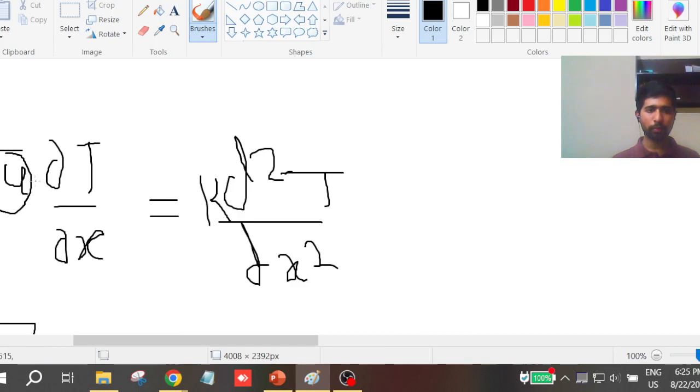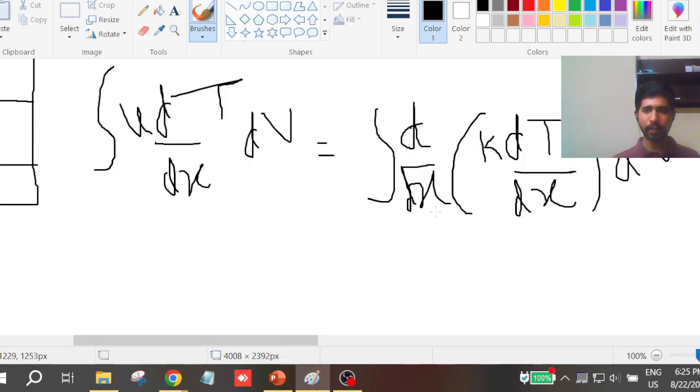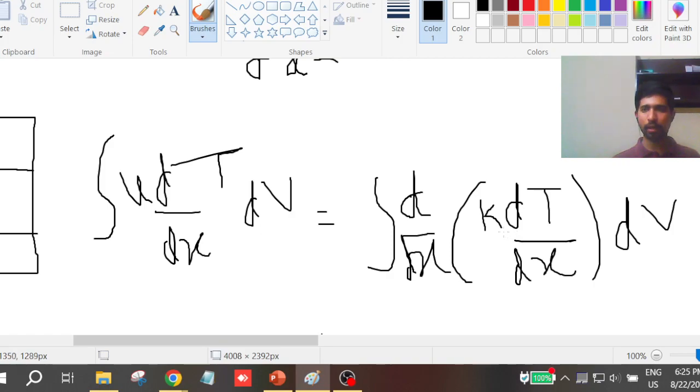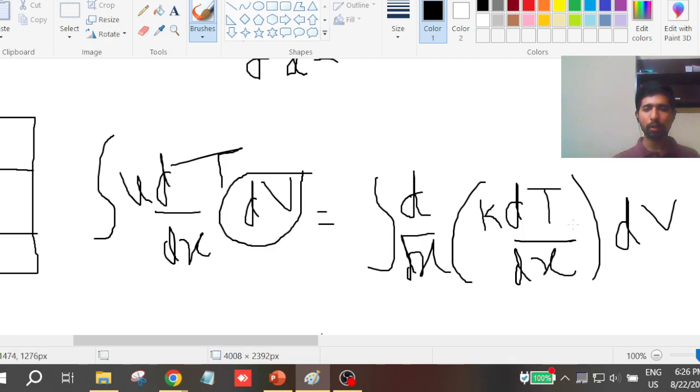So this is the partial differential equation which you are all very much aware of. But from here you have to understand things. Now what usually is done in the finite volume method, and maybe this step was somehow not in the notes, we apply something called the Gauss divergence theorem here, especially when we have gradient terms. Here also the gradient is there, here also the gradient is there. So this volume integral can now be converted into a surface integral.